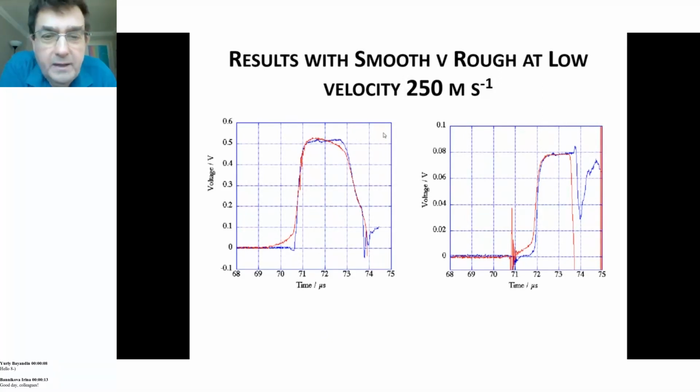And what we see here is the gauge at the front. We can see there is ramping in the gauge. Not an issue. Again, you can say that's due to the time it takes to collapse down that roughness on the surface. That's what's happening. On the front and on the back, you can see that the roughness is affecting the rise time, but the ultimate stress you record is very much preserved. Good.